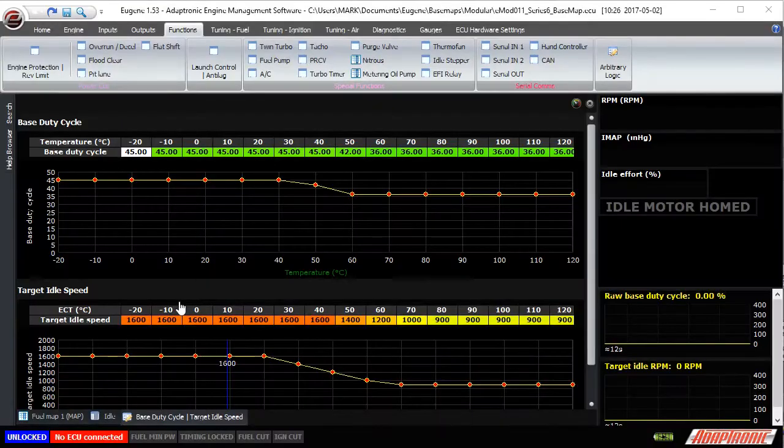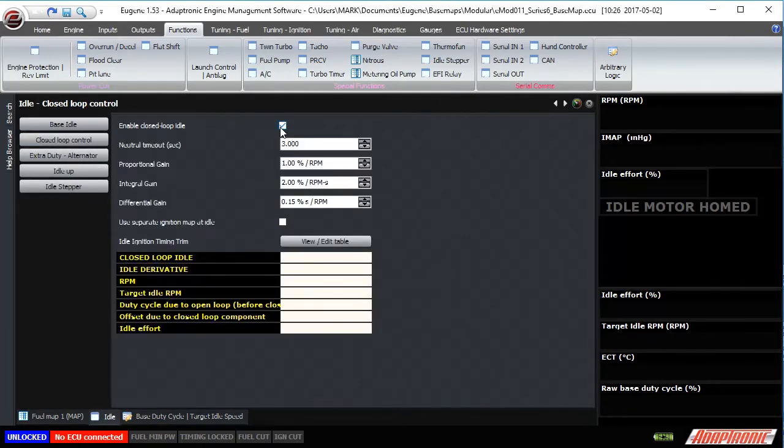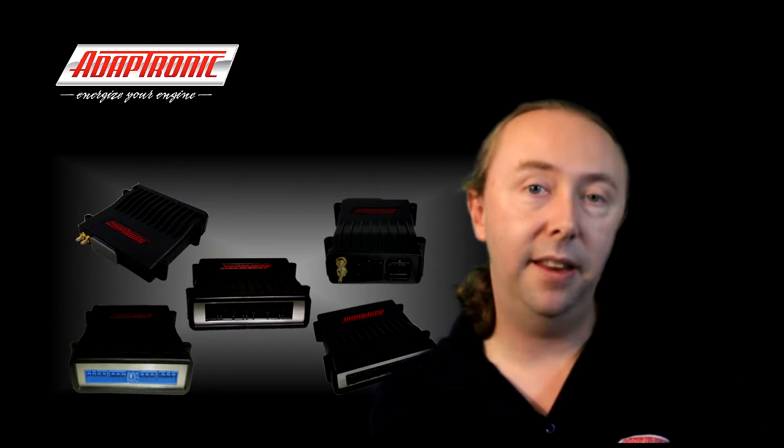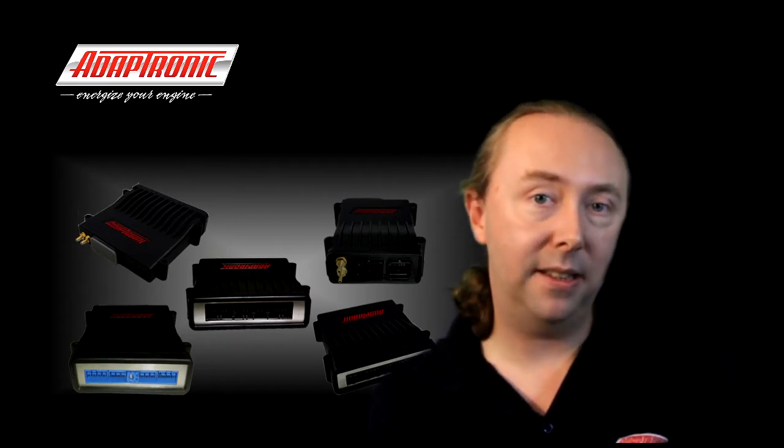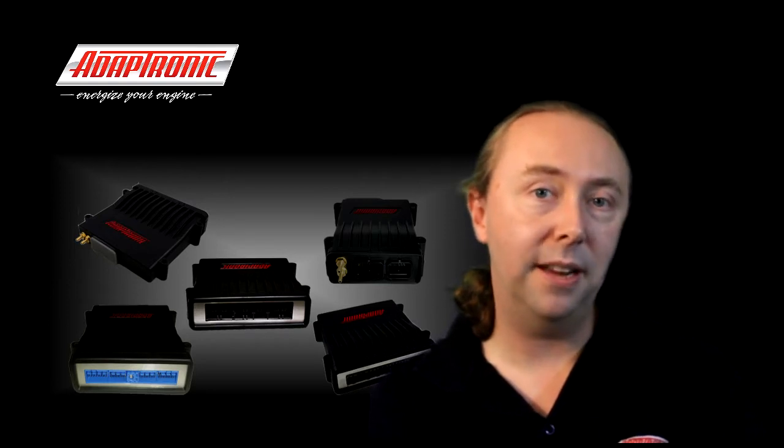Now the other way that you can do it is you can enable closed loop control, and then once you've set up closed loop control and it's working correctly, you can just look at the value once it's actually stabilized on the target and then write that into the base idle effort table. Now that's a lot easier, but you need to have the closed loop setup working first of all.